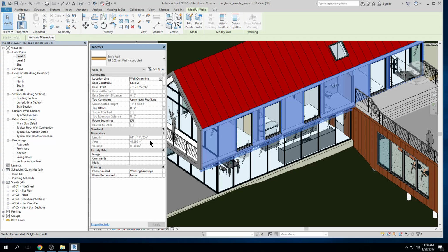And you need to show the difference between the existing elements that are staying and the elements that are going to be demoed and taken out, and then the new elements that are going to be built in their place, right? Makes sense. In AutoCAD, we do that with line types. So things that are going to stay are very grayed out. Things that are going to be demoed are dashed, and things that are new are bright and have continuous lines, right?